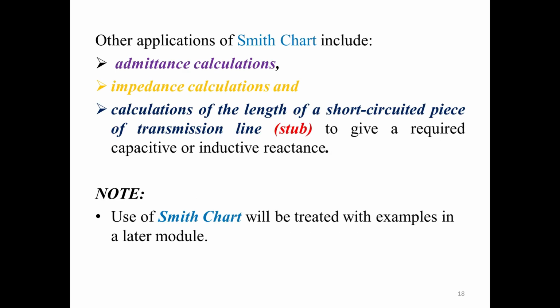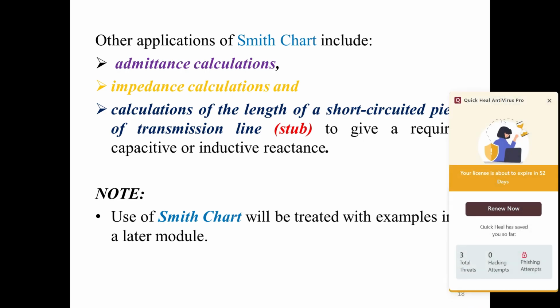Other applications of the Smith chart include admittance calculations, impedance calculations, and calculations of the length of a short-circuited piece of transmission line to give a required capacitive or inductive reactance.